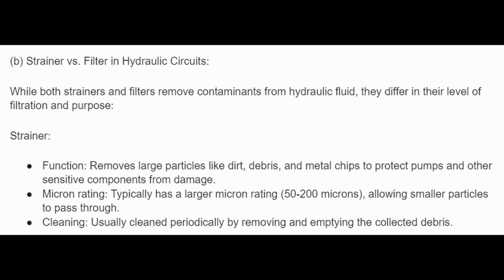B. Strainer versus filter in hydraulic circuits. While both strainers and filters remove contaminants from hydraulic fluid, they differ in their level of filtration and purpose. A strainer. Its function is to remove large particles like dirt, debris, and metal chips to protect pumps and other sensitive components from damage.